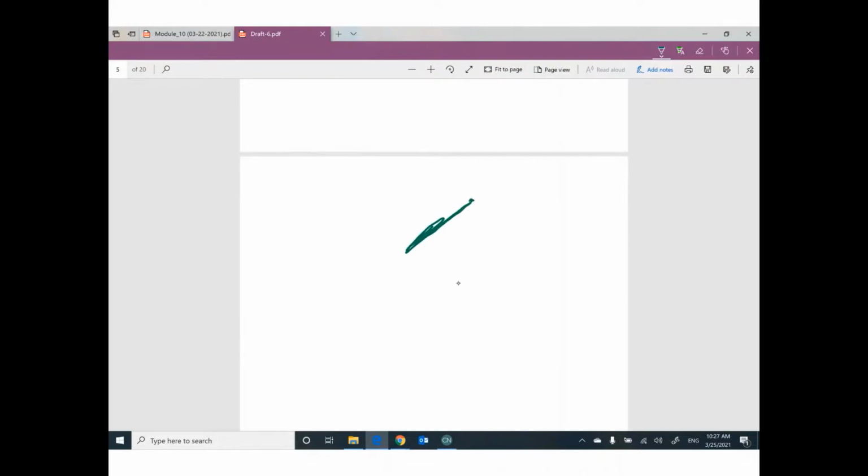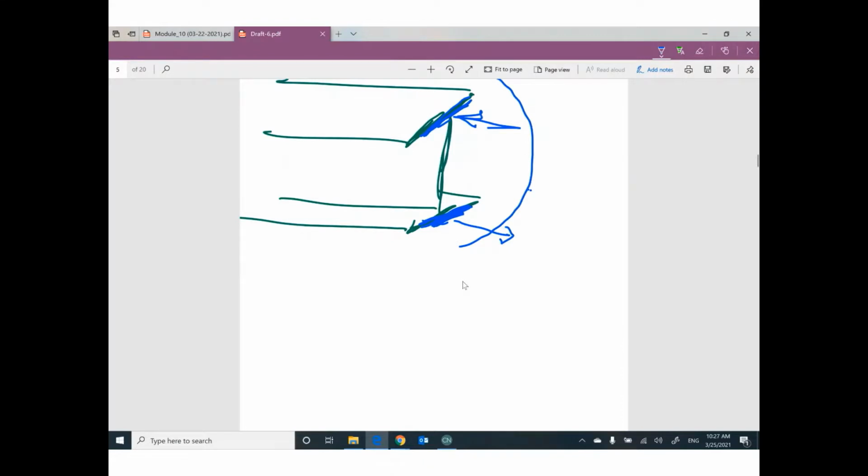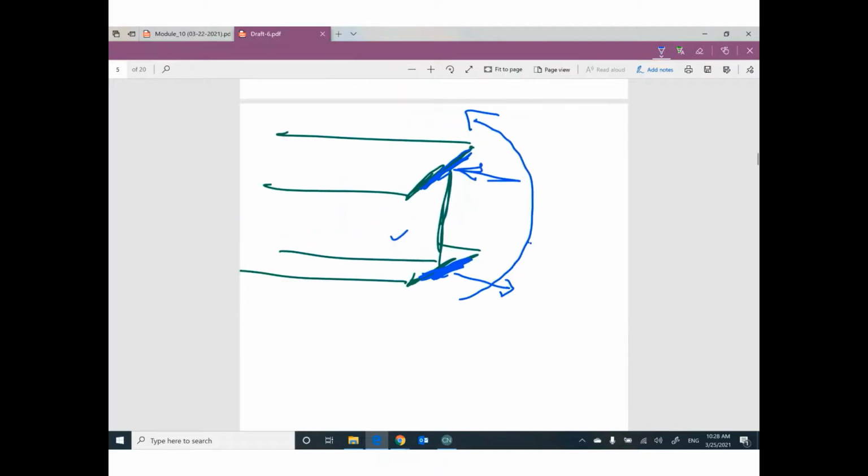If you have cross section like this, your bending moment on the beam like this. Mainly, this moment is supported by the bottom flange in tension and the top flange in compression. So if you would like to transfer moment between this part and another part, like a column or another beam, you need to connect this flange and this flange to the other part. If you did this, we can transfer moment. If you didn't, we have only shear by this one.